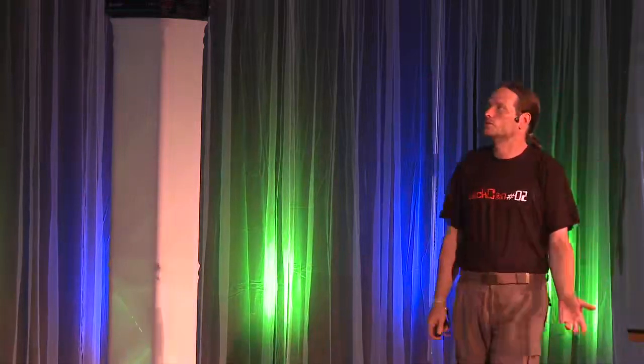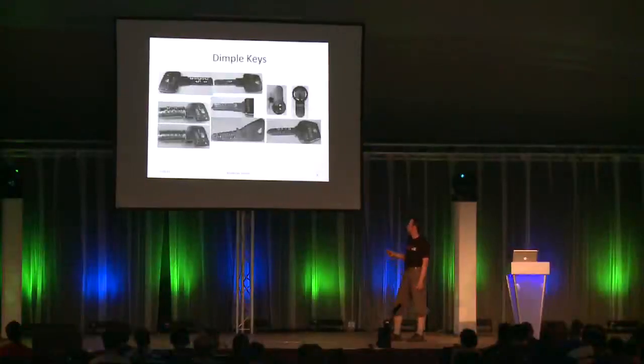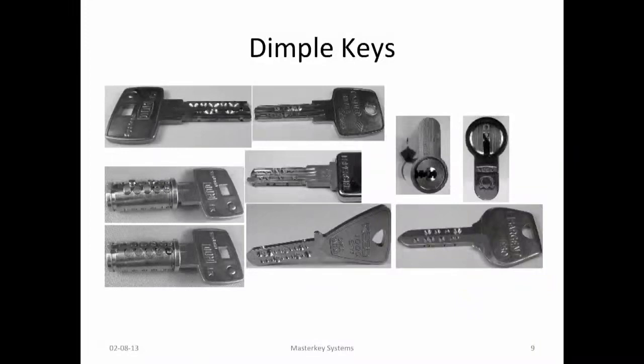Also we use dimple keys, which is principally the same. Dimple keys just have these grooves here on the key base and at 90 degrees, but it's always the same. So dimple keys look secure, but in principle it's the same key. When you see a key here with many, many dimples, what do you think how many pins this side has? It looks like 50 pins or something. This is only 5 pins in a row, which can really be checked.